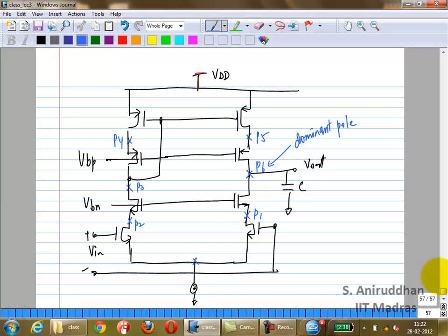We have two gate source capacitances, whereas in the other cases, you have one gate source capacitance plus a drain bulk capacitance. So from a high level point of view, you'd expect P3 to be the most important one. Quite possibly that's true.